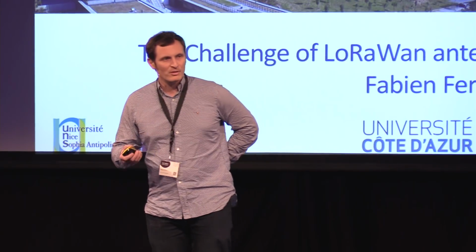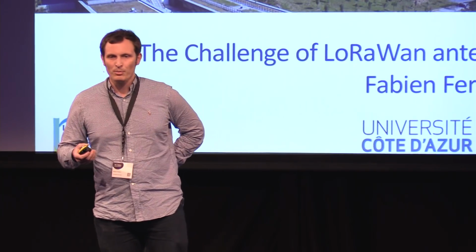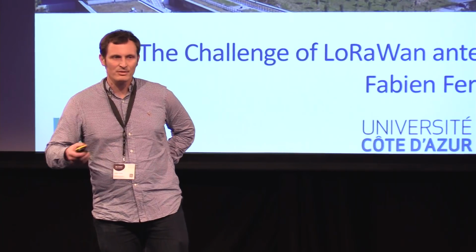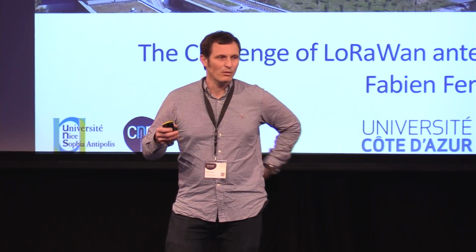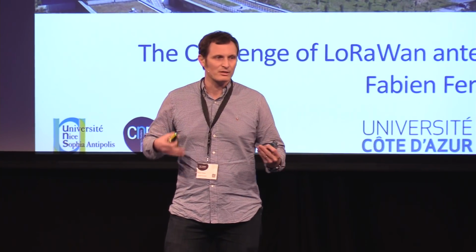So why? First, because, for example, Zigbee is using the 2.4 gigahertz band. So it's 3 times the band you are using for LoRa. And also, it was a technology with quite short-range communication capabilities. And when you are thinking of LoRa, LoRa is long-range. So there is a strong expectation to have long-distance coverage with this technology. But LoRa is also using a sub-gigahertz band, so near 900 megahertz. And at 900 megahertz, the wavelengths start to be very large. It's close to 34 centimeters.